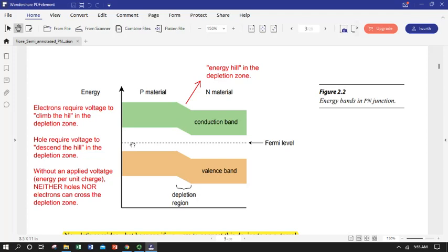We've shifted where the charge carrier's average energy level is. And in the middle, if you wanted to measure the Fermi energy level right in the middle of this depletion zone, it's dead center, which is what we'd expect from an intrinsic semiconductor. So if the Fermi level has to stay constant, which we're just going to assume it does, something else has to shift because the material is continuous.